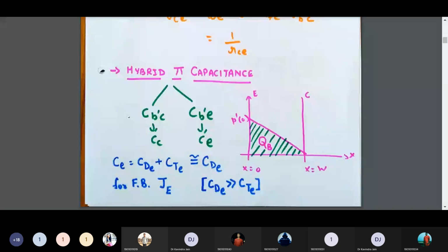As we were discussing, if it is a PNP or NPN transistor, or rather in a broader sense, if it is a transistor, then there are two junctions. One is the JE junction and another one is the JC junction. I repeat, one is the JE junction and another one is the JC junction. So presently the condition is my JE junction is forward biased. If my JE junction is forward biased, then my JC junction is reverse biased. JC means junction at collector, JE means junction at emitter.